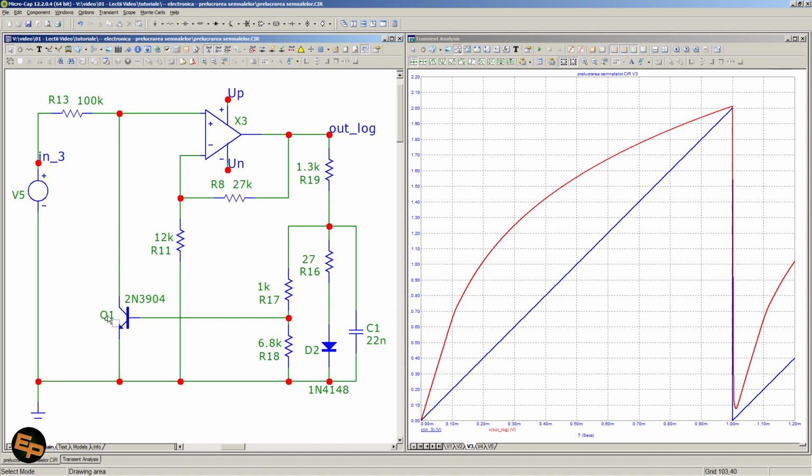It can actually get down to zero if it needs to. Okay, so we need to make this transistor turn on and off, and not just on and off, but start to turn on gradually based on what voltage we have on the output. And for that,